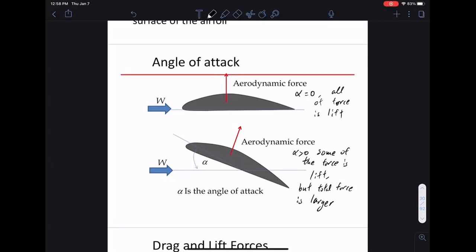If you don't need your maximum power, then you don't operate at the optimal angle. By changing the angle, you change the lift force, and changing the lift force changes the power you generate.